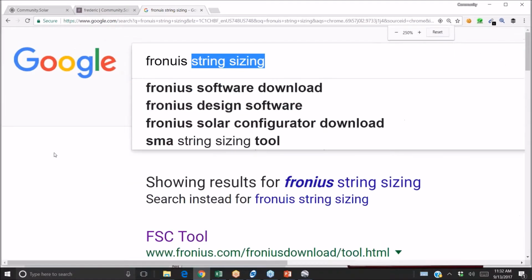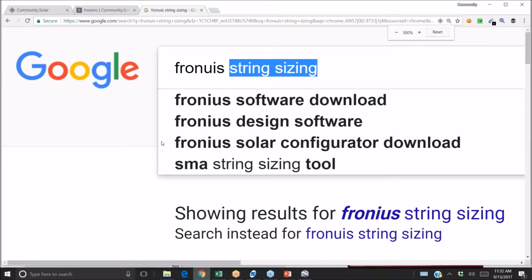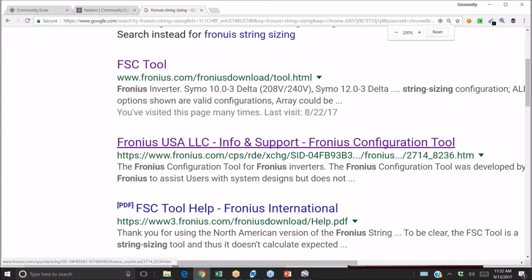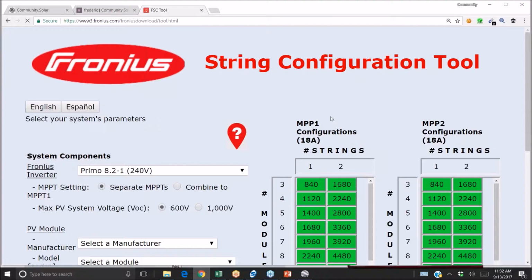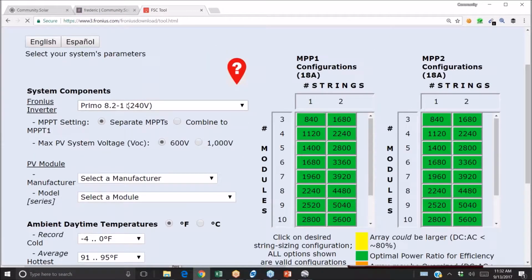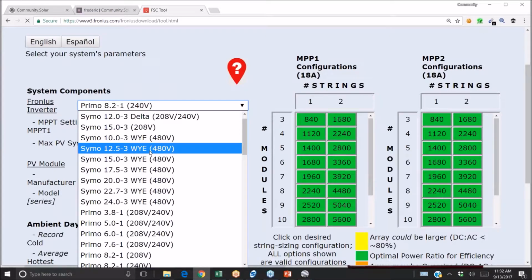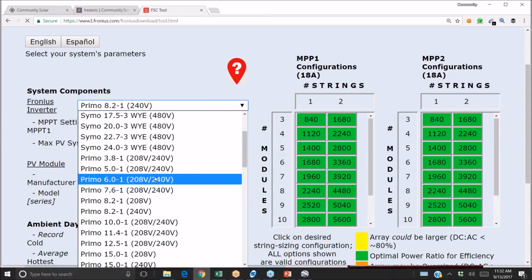If you just Google the inverter manufacturer name and string sizing, you'll get the software sizing tool provided by the manufacturer, which is free. The manufacturer wants you to be able to figure out what inverter goes with what module. Some of the battery companies are used to off-gridders who are maybe not even following code, but piecing together the design based off these temperature coefficients, etc.